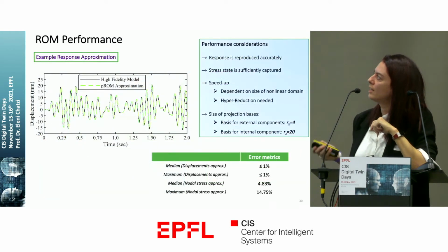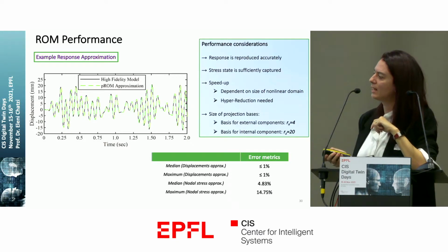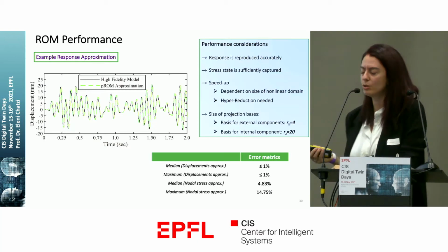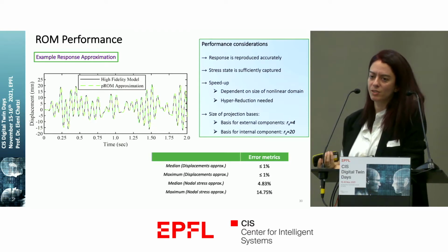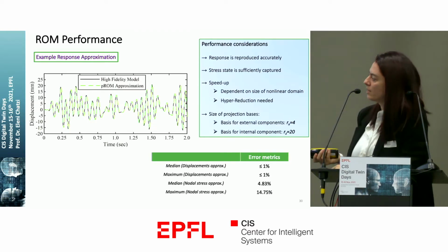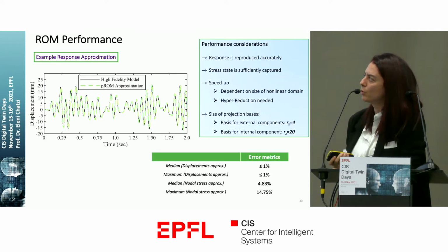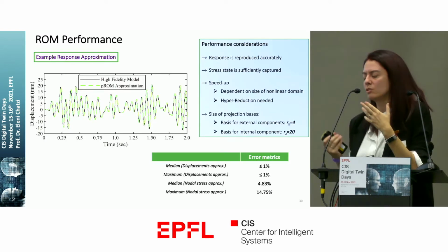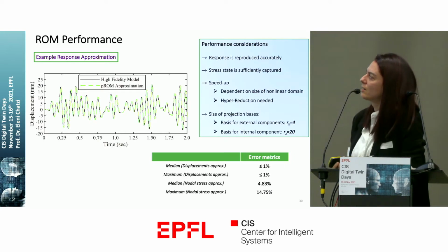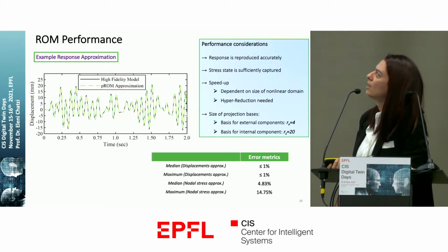And so at the end of the day, we can again have a reduced order model that offers a very good approximation of the high fidelity model. And here we have to say that very good depends on the level of accuracy that one wishes to obtain. For engineers, this can be quite different. For us, it more commonly depends on the approximation of displacements and the stresses that can be produced by these models. And this is because these are aspects we're typically monitoring. So the strain, and indirectly the stress, and also the deformation in its dynamic sense.